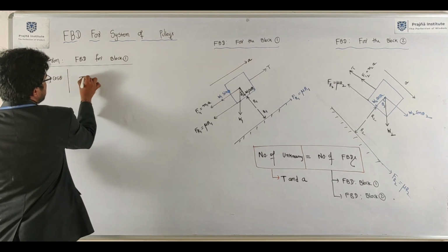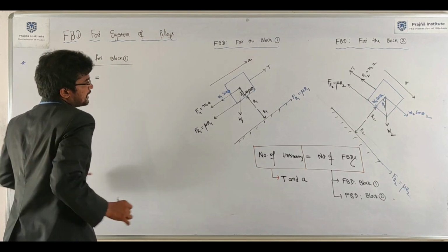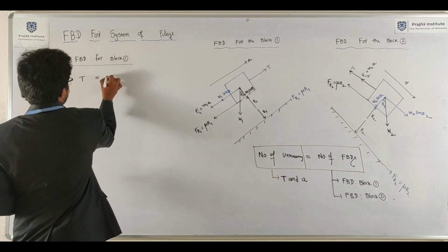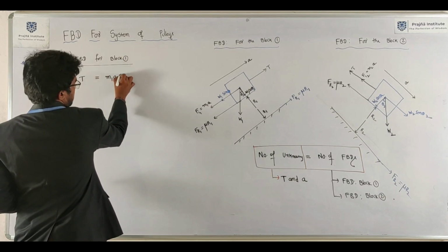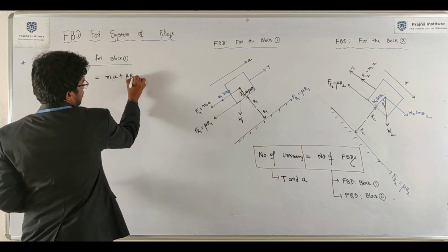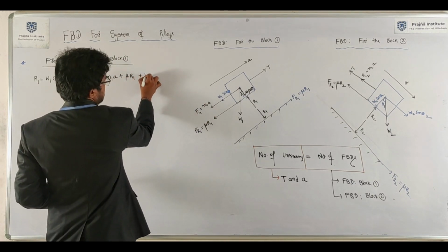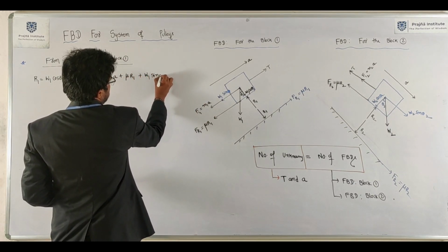Tension T equals M1A plus mu into R1 plus W1 sin theta 1.